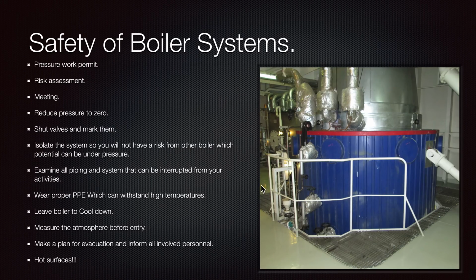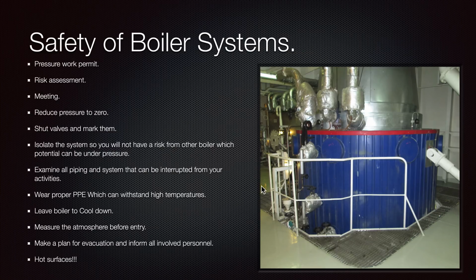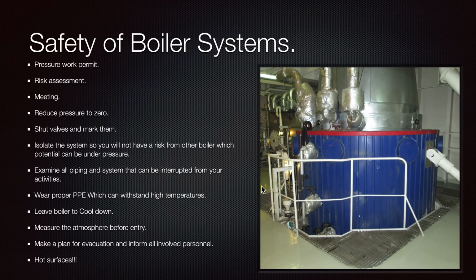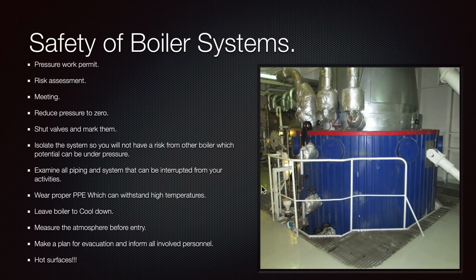Be careful, there are a lot of hot surfaces outside the boiler and inside the boiler, and always make a plan of evacuation and inform everyone. One person always monitors outside while the other person is inside.